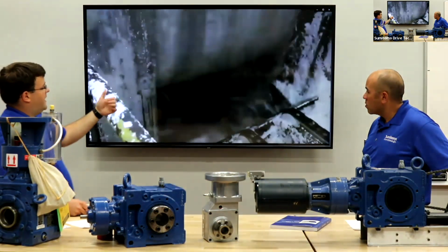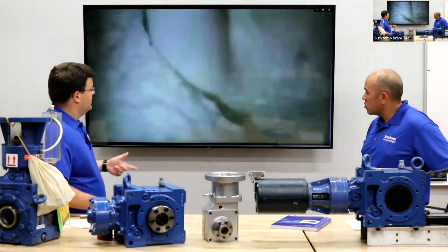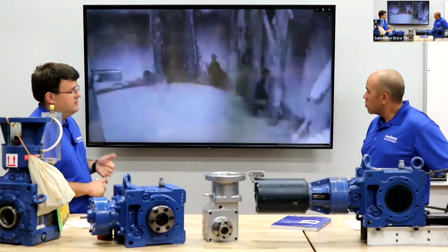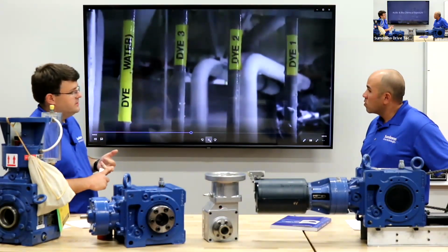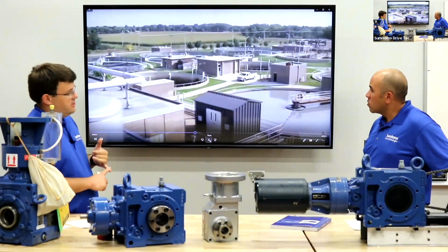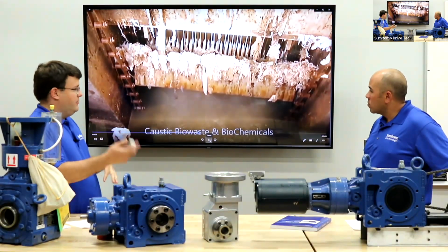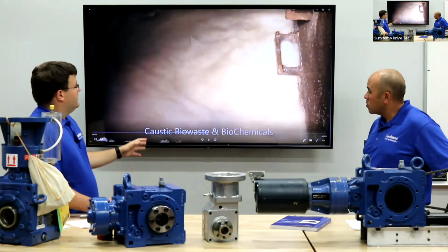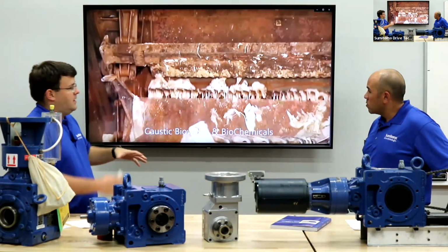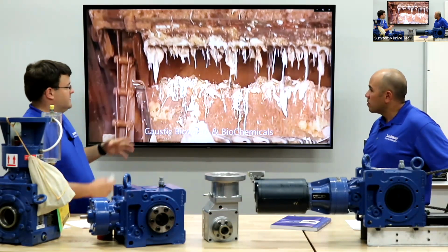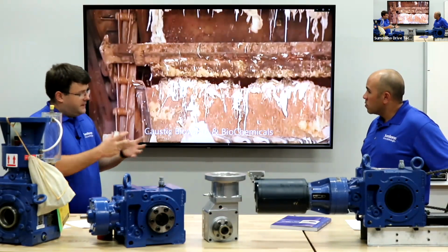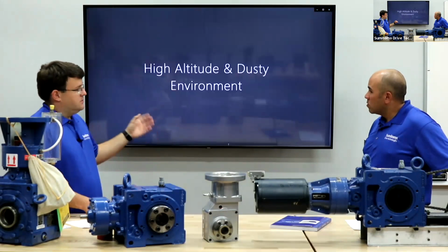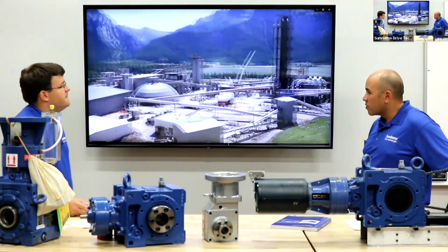Same thing here with high or low temperature. If it's too hot, we change the oil. If it's too low, we change the oil and change the breather, change the seals so they don't start cracking. Yep. If it's indoor, outdoor, we change different things. All these different things going on here, we have to remember to compensate for on the options side. Because like I said, it doesn't necessarily change the gearbox physical frame size, but it may change what options we put on the outside. The accessories, the coatings.